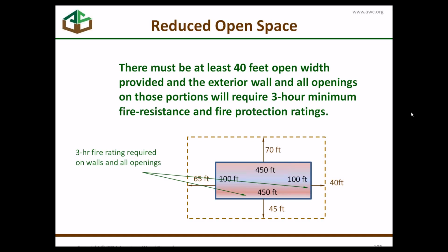Okay, and the next question is, would you explain the difference between type A and B construction, for example, type 5A and type 5B? That's a great question too. Back at table 503, we had the A and the B at the top under various construction types. The A typically designates 1 hour rated construction for your structural elements in the building.